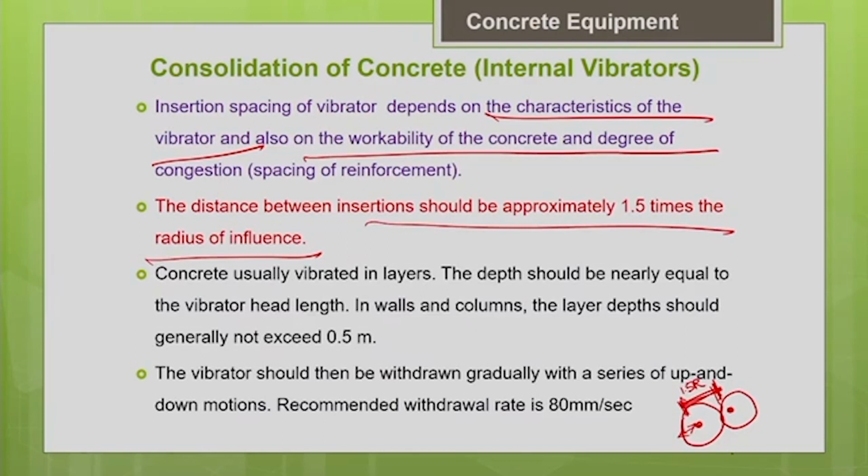If it is a stiffer mix, you have to reduce the interval; if it is a highly consistent mix, you can increase the interval. It also depends upon the spacing of your reinforcement. If it is very densely reinforced, you have to reduce the spacing. So it all depends upon the characteristics of your concrete, the spacing of your reinforcement, and the vibrator type.